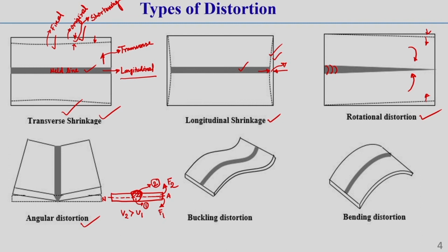So, due to these things, you can see that due to shrinkage of this volume of molten material, generally the shrinkage force on the top side will be much higher than on the bottom side. Once it is solid, it creates a higher force on the top side, due to the higher volume of material, than on the bottom side of this neutral axis. Due to this high shrinkage force, once it solidifies, as the top side force is more, the plate is generally bent